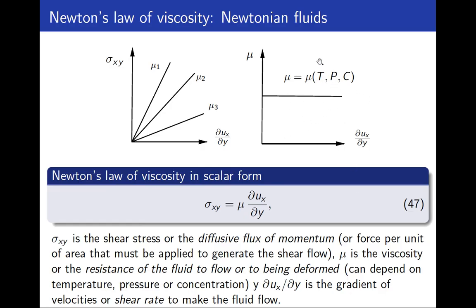So this is another characteristic of Newtonian fluids, that the viscosity is constant as long as the temperature is constant. Here, for instance, we have three different values of viscosity, and these curves can represent different temperatures. This curve represents the case at 20 degrees, this one at 30 degrees, and this one at 50, because the viscosity decreases with an increase in temperature.